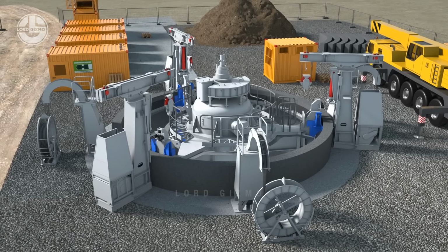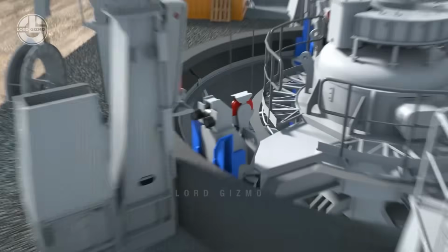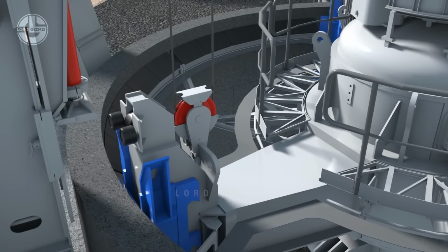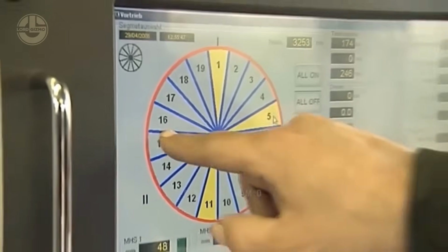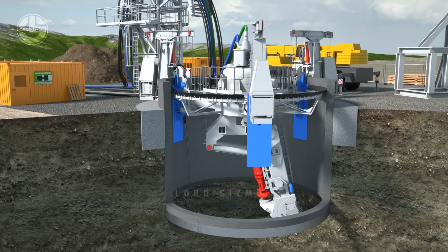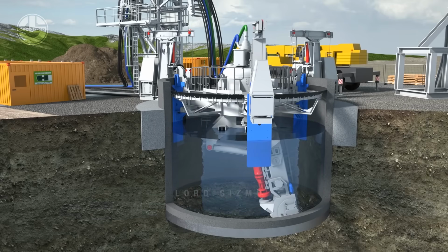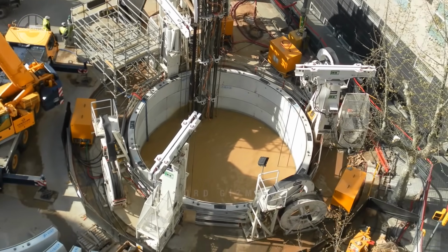For cutting the predetermined profile in the necessary portion, the cutter boom can be manually operated or programmed to operate automatically. To maintain the equilibrium of the groundwater table in the surrounding geology, the shaft is kept full of water while it sinks. The optimal excavation rate can be attained by adjusting the cutting movement and speed.